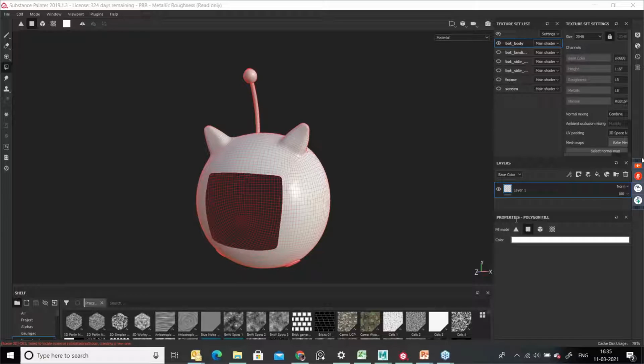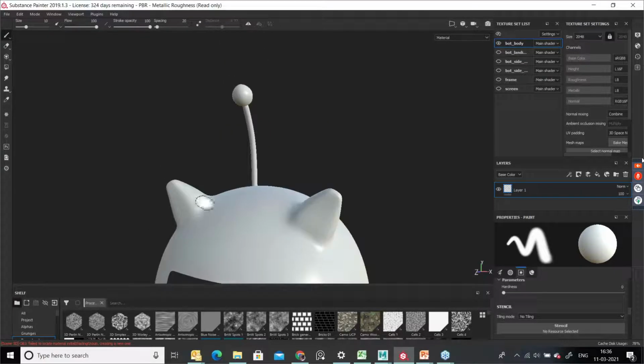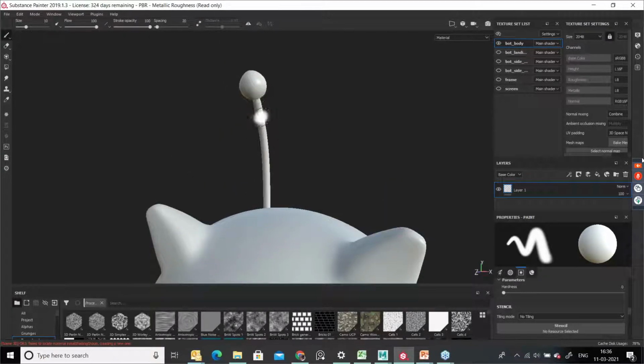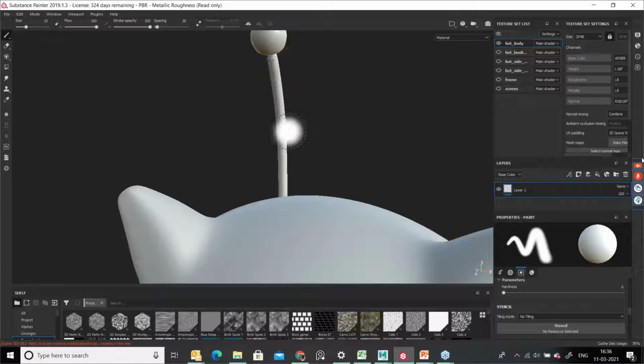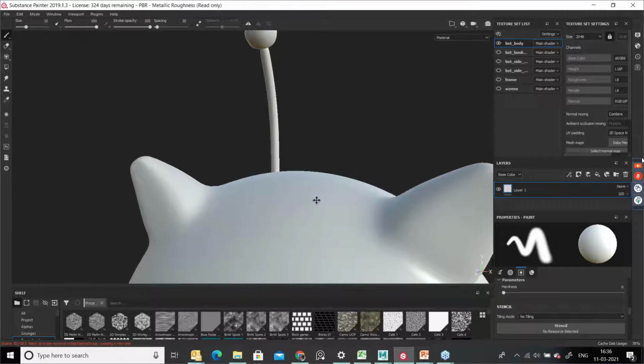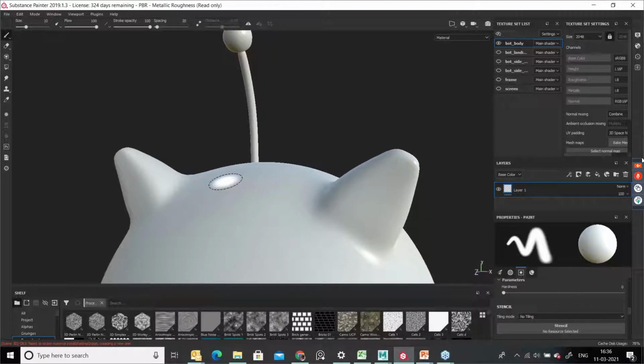See, anti-aliasing, nothing, man. When you are going very close to this, you can find out the dot line, right? When you go very closely, you can find the jaggy edges over here. Those jaggy edges you can remove when you increase the anti-aliasing value in the anti-aliasing settings. Then you won't get this jagginess. It will give you a smooth surface for your visual experience. That is anti-aliasing. And in rendering also, it will give you a proper output.